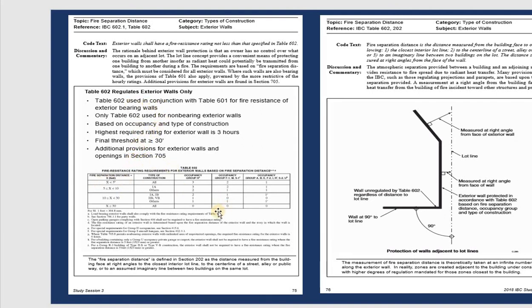So this is the detail where they showed you some kind of type of construction with occupancy, and after that the group one. So all of them have a specific rating hour you need to require. They show 3 or something like that. That means 3 hour, 2 hour rating wall you need to design for. And this one they have the group 1A, or 1B, or 2. They show you like that for the detail.